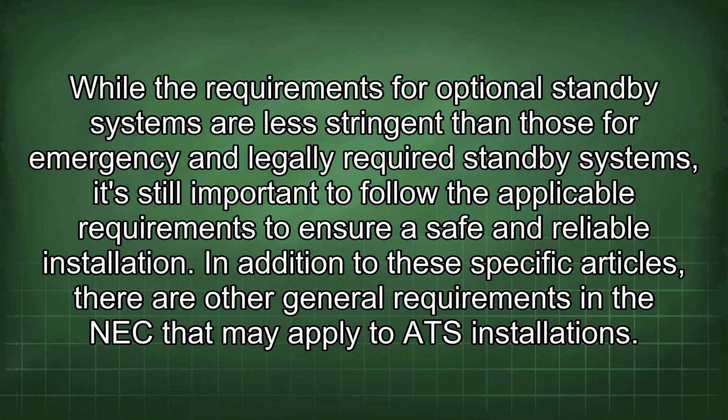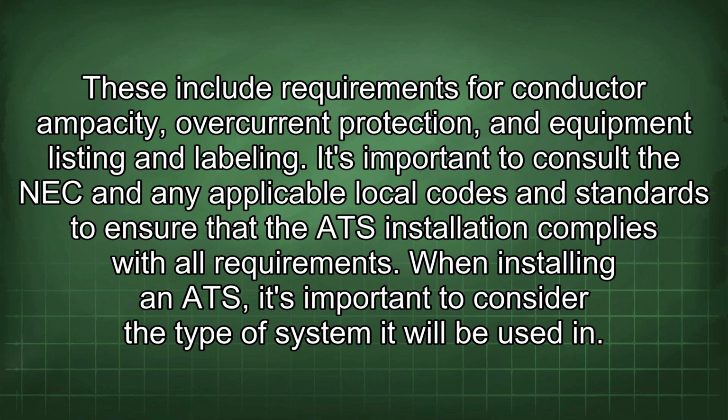In addition to these specific articles, there are other general requirements in the NEC that may apply to ATS installations. These include requirements for conductor ampacity, overcurrent protection, and equipment listing and labeling. It's important to consult the NEC and any applicable local codes and standards to ensure that the ATS installation complies with all requirements. When installing an ATS, it's important to consider the type of system it will be used in.